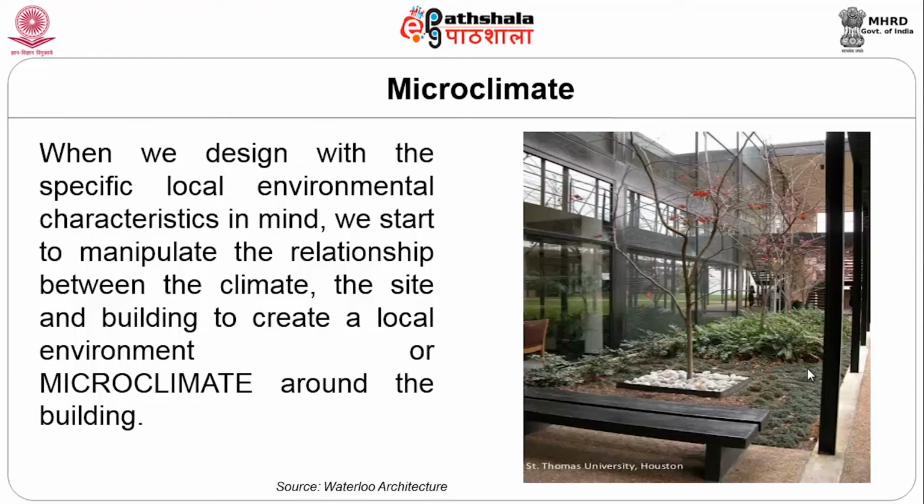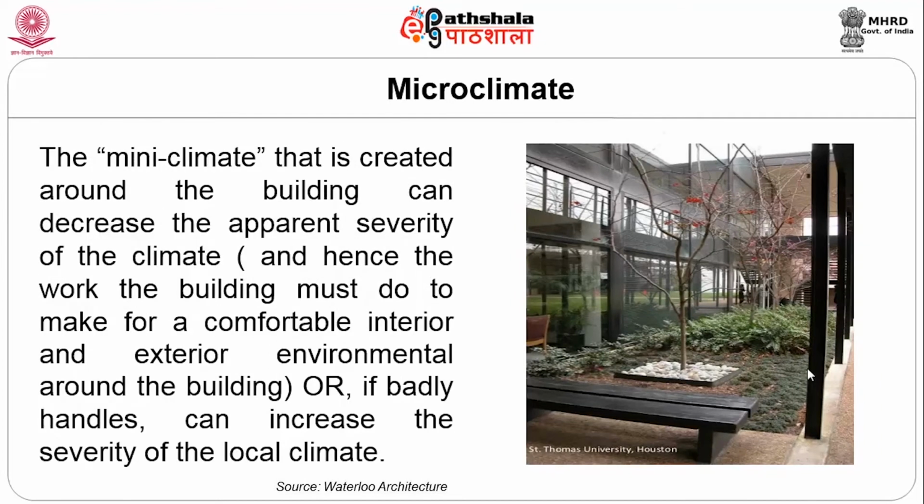So, when you look at your individual site to finally construct, you need to take into consideration the microclimate of that site. The mini climate that is created around the building can decrease the apparent severity of the climate, and hence the work the building must do to make the building comfortable in the exterior environment is much lesser. And if this is not handled properly, we will actually increase the severity of the local climate, either make it colder or make it hotter depending on the place we are in.